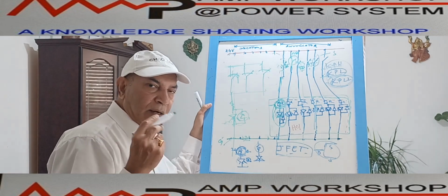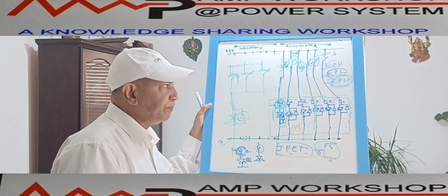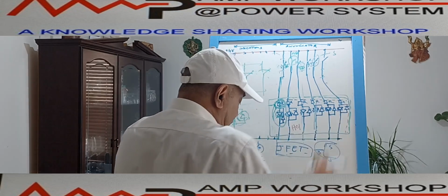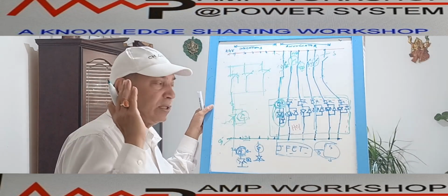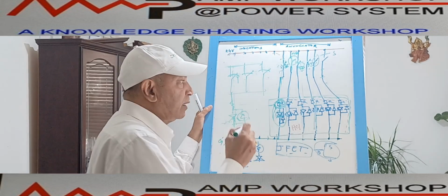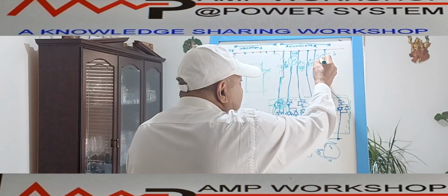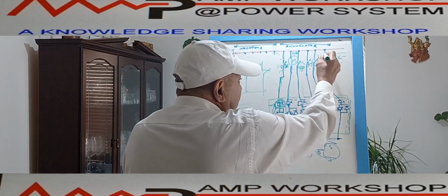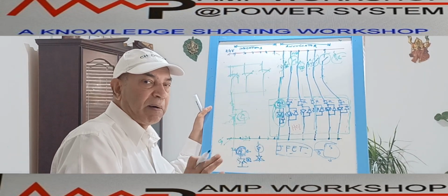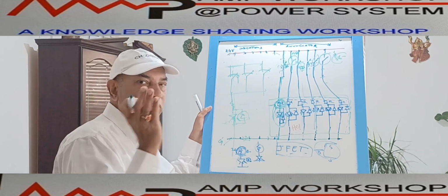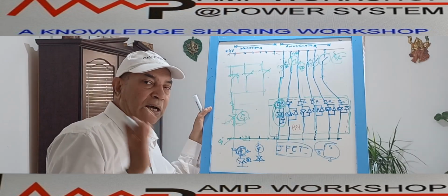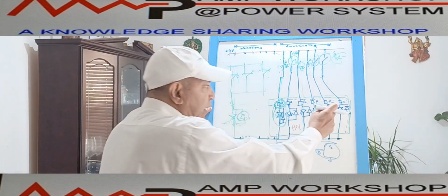That the SF6 gas pressure is not healthy. Similarly, suppose if we want to monitor any other parameter, suppose there is a tripping in the downstream, so that needs to be monitored over here. In that case, from the downstream there is a lockout relay. That lockout relay contact we can bring over here and connect over here. Suppose this switchgear is feeding power to another feeder downstream. In that case, the downstream condition we need to monitor. So we can connect the downstream contact over here. It will indicate that downstream is faulty. So that also we can monitor over here.